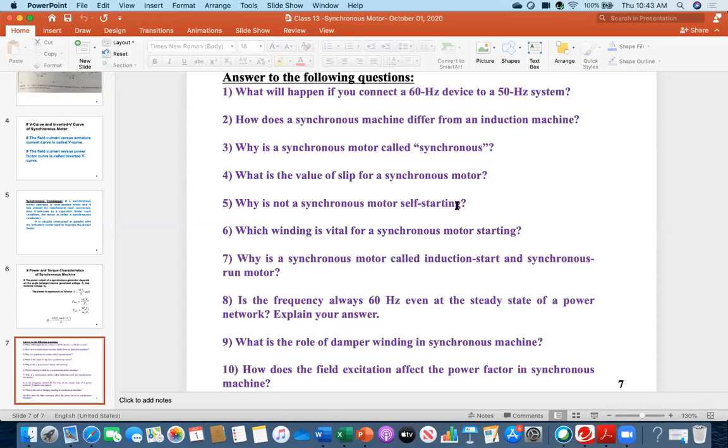Plus, what is the main reason? Because it has the inertia. Rotor has inertia. So that's why you need the help of the damper winding. You said the hunting, but hunting is related to synchronous generator, not the motor. I'm coming to that point soon.